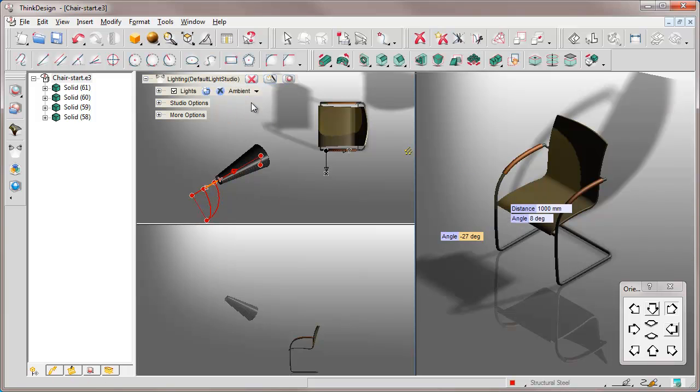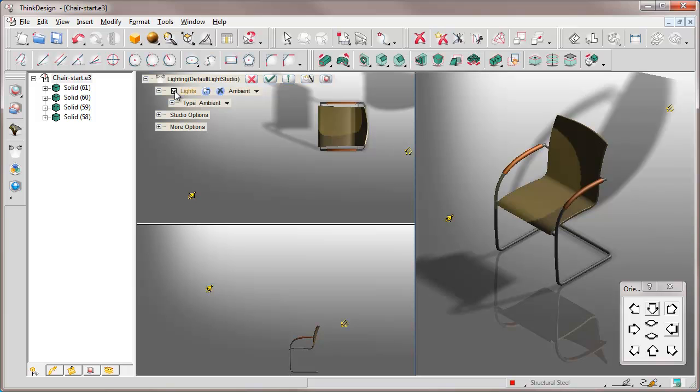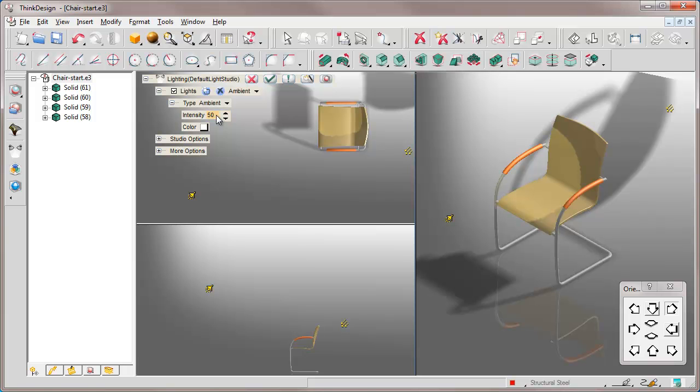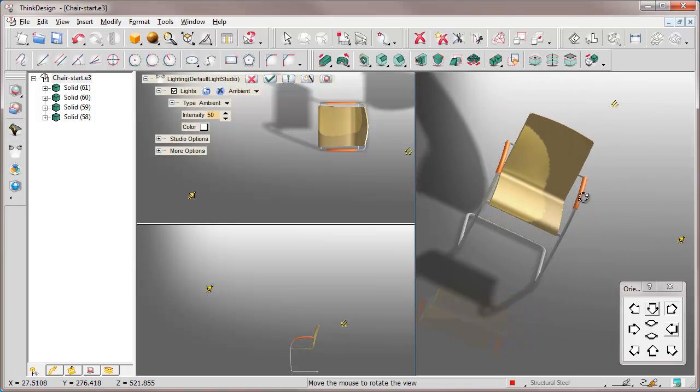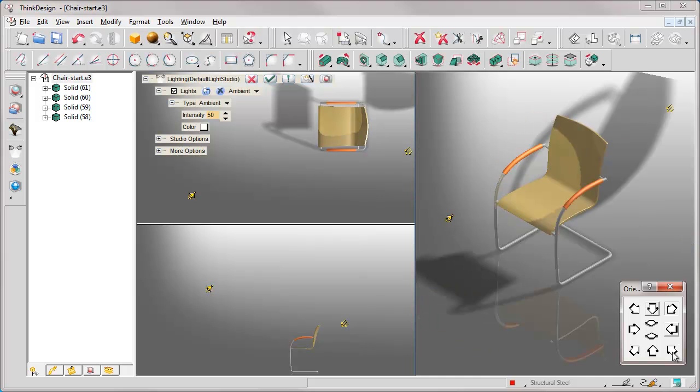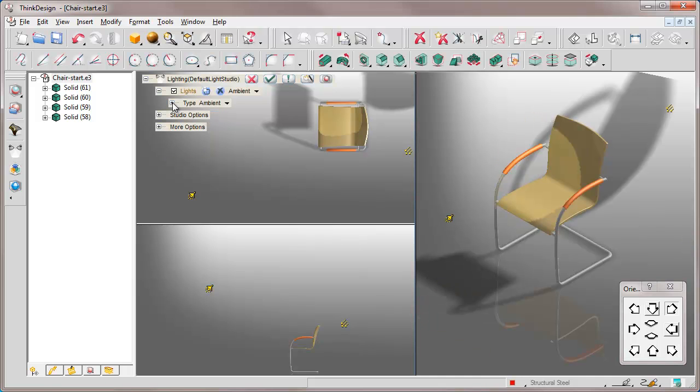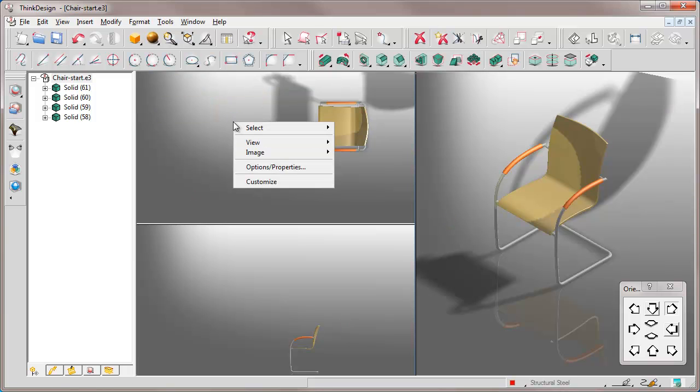Once we get a satisfying result, we can confirm and go by activating the ambient light. The ambient light is a diffuse light which illuminates the object from all directions. We switch the light on. The only things we can control of this light are color, that here we leave white, and intensity, that we bring to 50. This value is enough to restore a look of the object very similar to what we had initially.